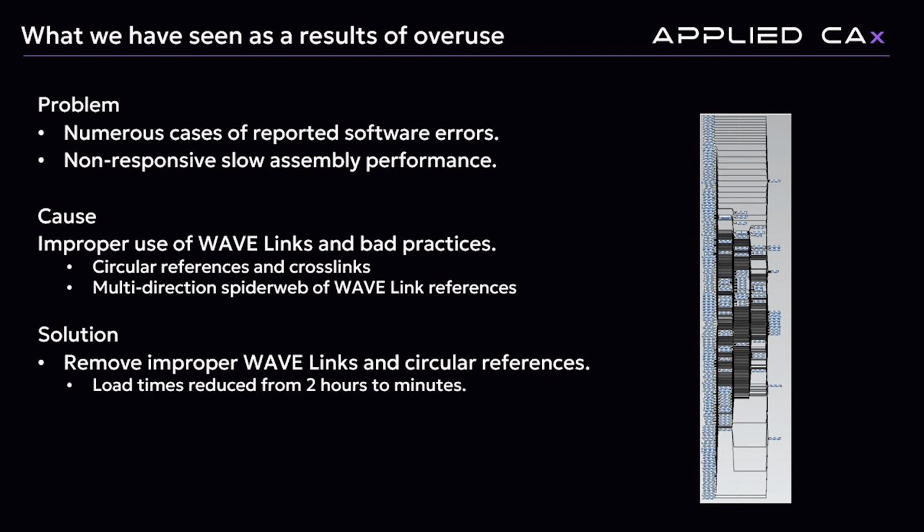Even we didn't necessarily know right away in some of the cases that it was wave linking, but the issues were reported as major problems. Sometimes not your memory error, but your PLM, XML, or just crazy errors, and then slow, unresponsive assemblies opening. In some cases 2 hours to open it, and then come to find out using the wave linker, as you can kind of see the preview here. Or not the wave linker, I can't think of the name right now, the relations browser.